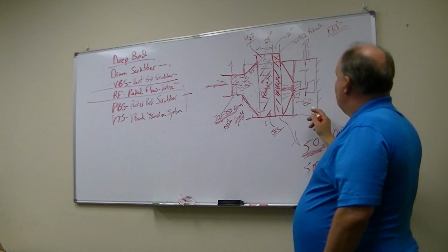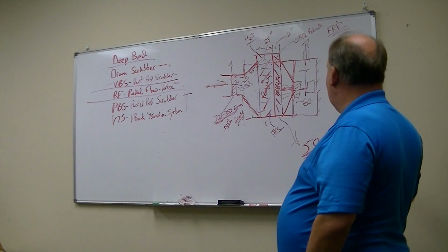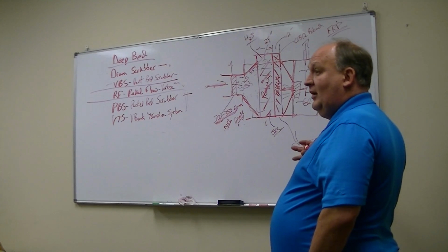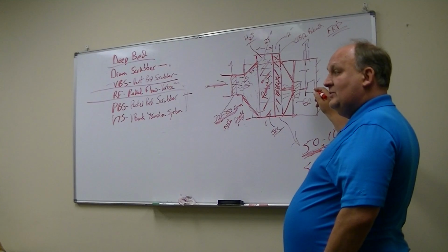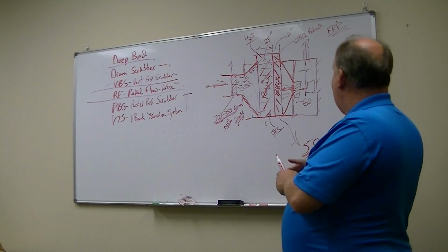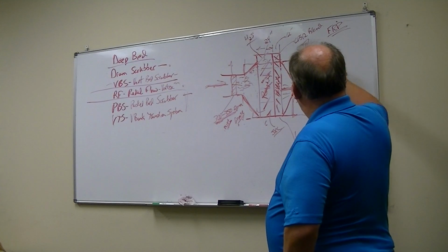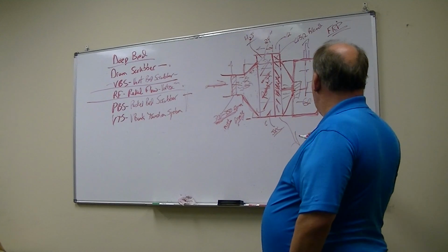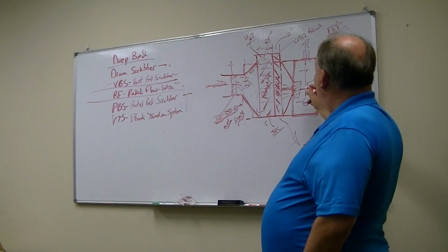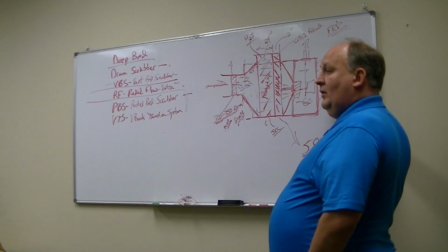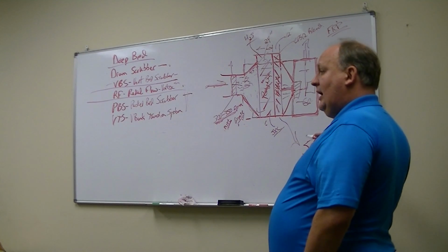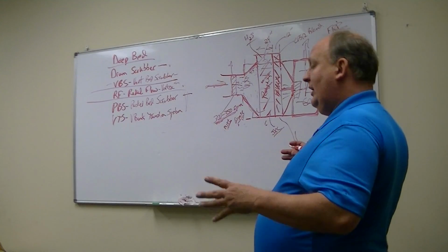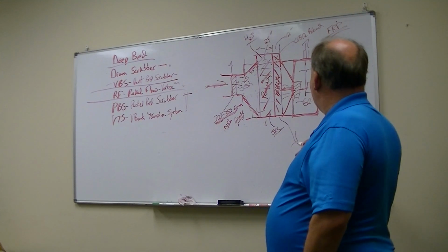So why would we want to do one or the other? Well, the advantage of this type is that it's typically a lot more quiet. We've made some super quiet systems using a plenum fan that are really nice, because you can even put sound insulation inside of this housing. The other is that a plenum fan is typically a lot less expensive than an external blower. In odor control, the external blowers typically have to be fiberglass, and they're fairly expensive blowers. So this blower is more expensive.